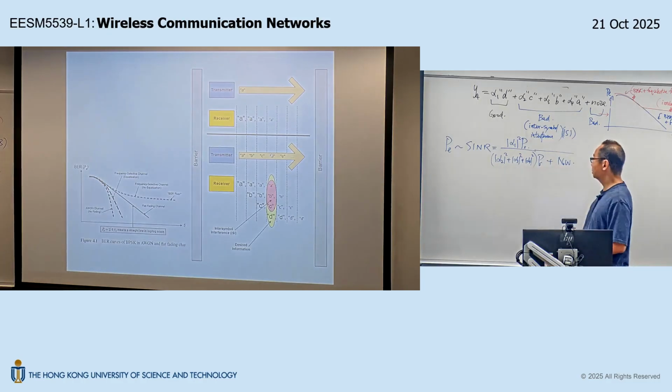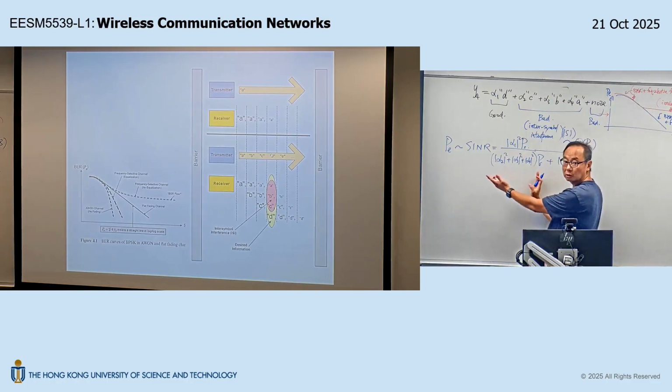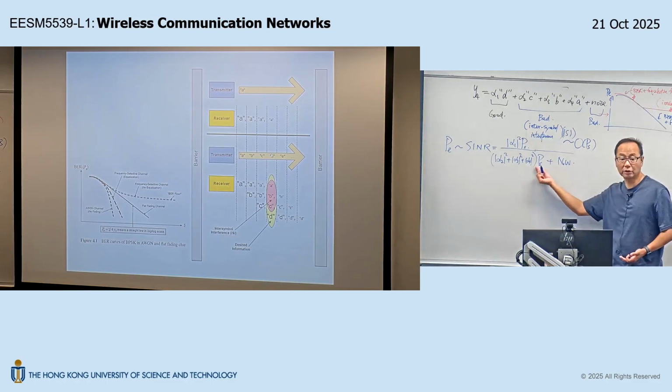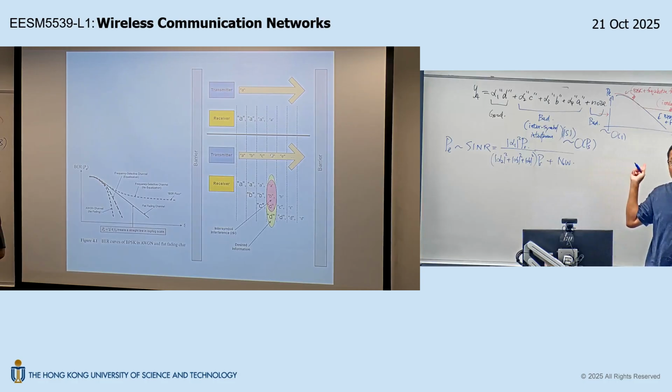From this, you can see that this interference term scales with the transmission power, right? This is, the interference power is proportional to the transmission power. Whereas the noise power is independent of your transmission power. Can you see that? Okay, if you think about this classroom as an analogy, when I'm talking, you hear my voice, which is a good term, hopefully, plus the background noise, right?